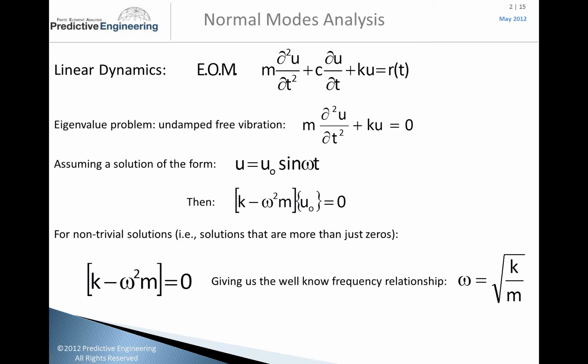And this is a pivotal point. There are no forces on it. So when you run a normal modes analysis, there are no loads. It doesn't exist. And that should be your first clue when you see this equation that you don't have loads applied, that all of your results are fictional, even though it's showing a displacement, a mode shape. It's just showing the relative displacements to the adjacent nodes. I like to think of it as a permissible mode of deformation of the structure. So no loads, and that's why they call it natural frequencies. It's how the structure wants to vibrate.